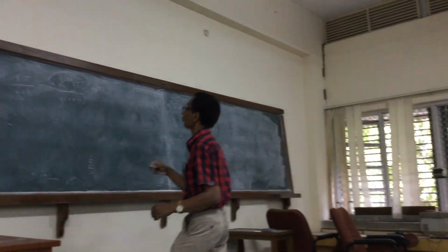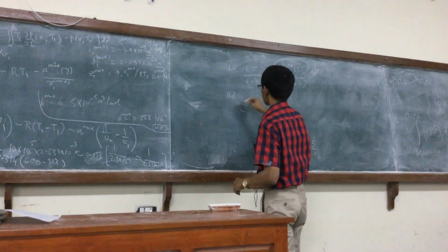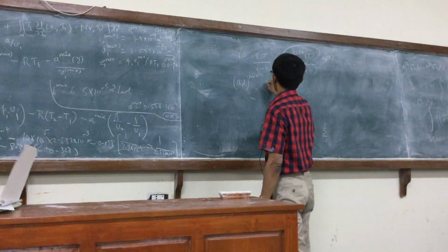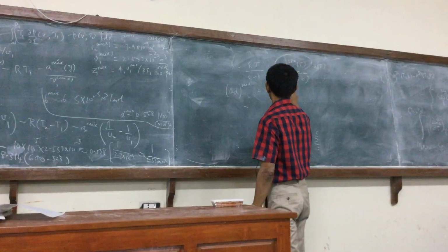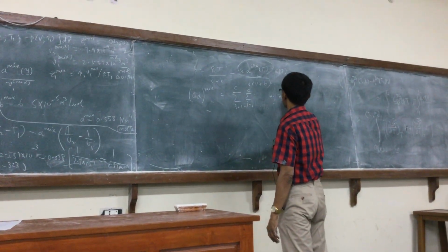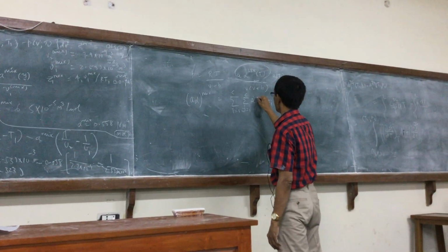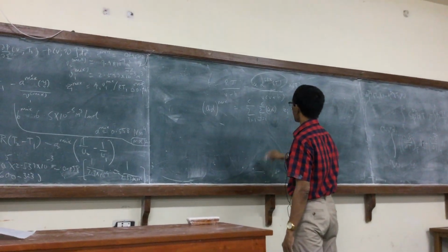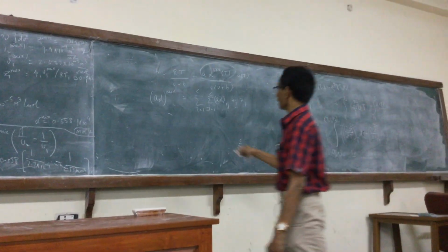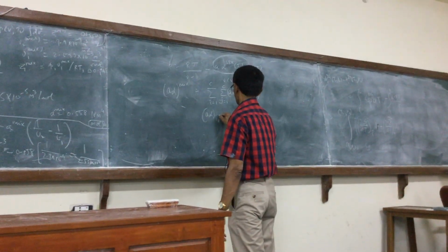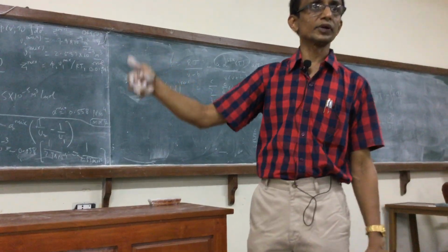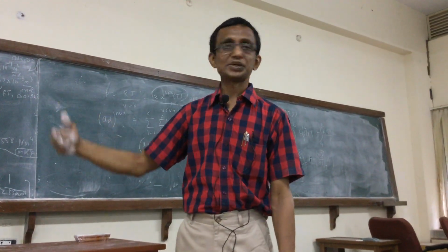Right? So I can write now A alpha, either it can be SRK or PR or whatever else you want to have, of the mixture would be the sum over i equal to 1 to C, z_i z_j times A alpha ij, right? Where A alpha ij would be the square root of... this is not the only form; some books also introduce another factor to the Aij formula.